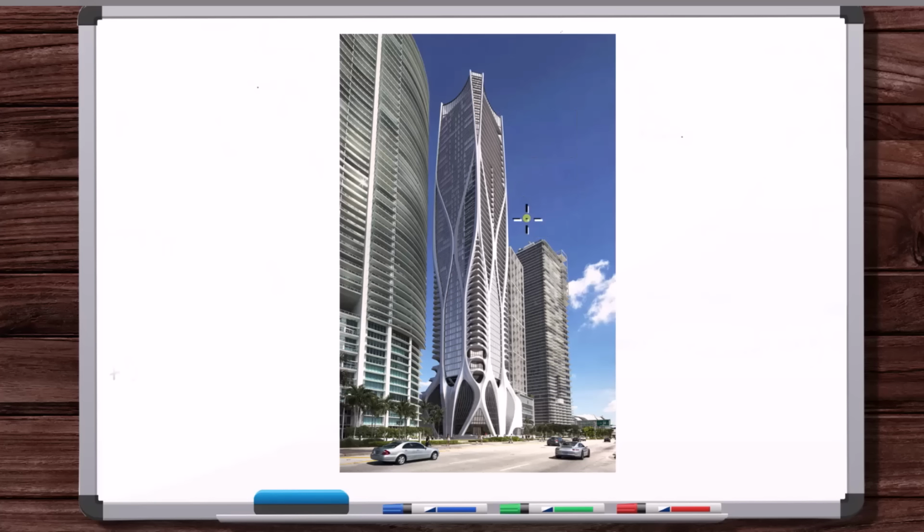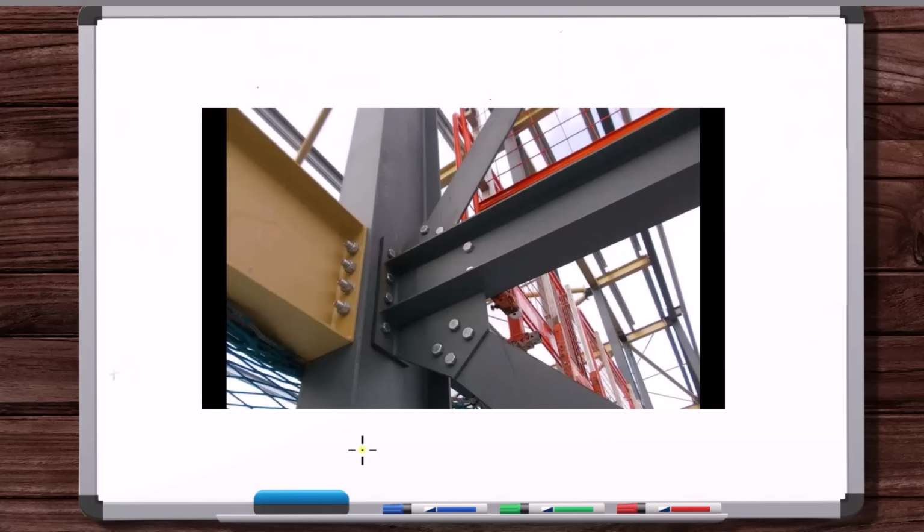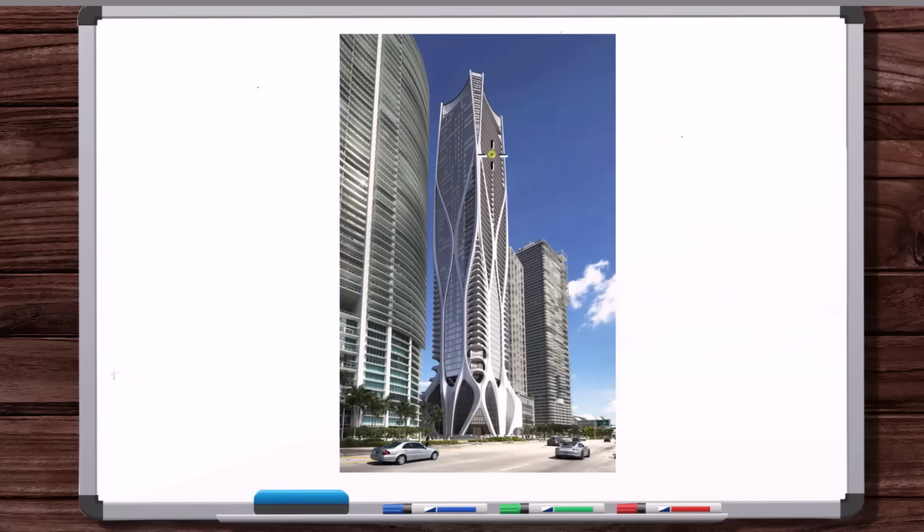Okay, but this was always confusing to me because it seemed like, man, you've got this whole structure as a free body diagram. This has to be a really complex free body diagram, this is going to take a while to make. Well, remember, all of the connected components, all of these connections, they're rigid. These are internal forces, right? We can ignore these forces in the free body diagram. As long as we brought those connections with us, we didn't remove those connections, there's no exposed surfaces here. The only exposed surfaces outside of the wind force, right? There's contact between the wind and the steel structure.